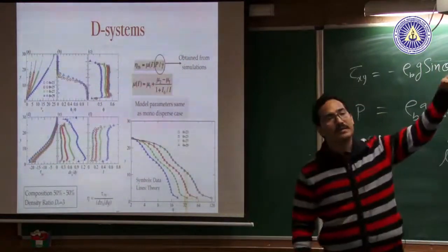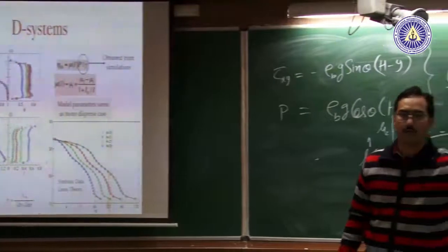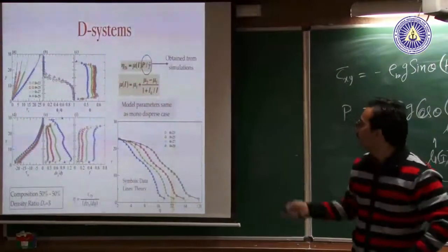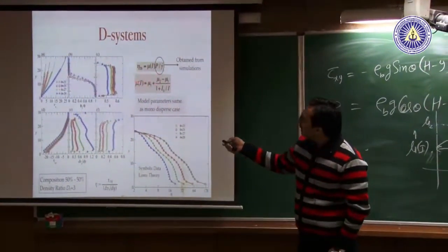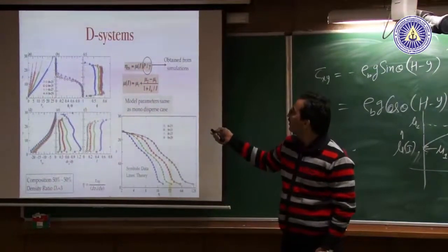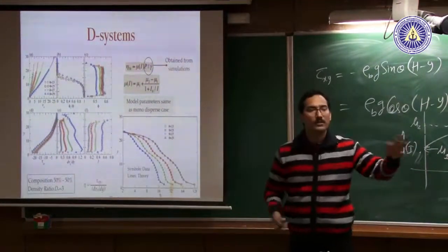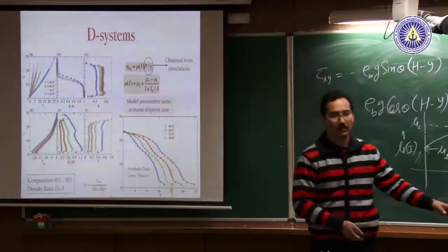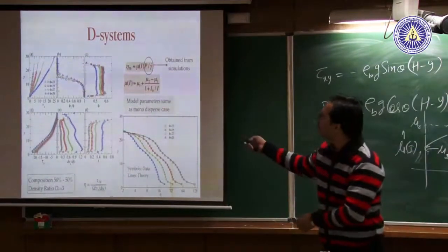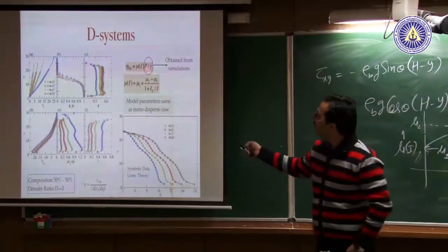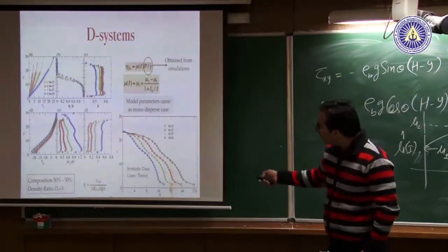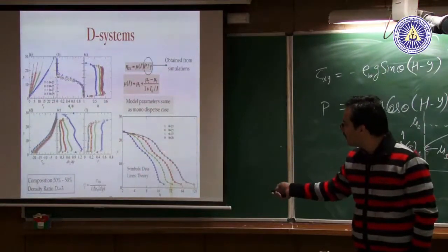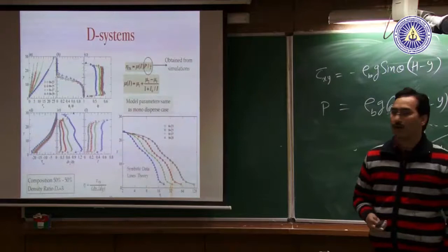I use the same parameters that I had for my monodisperse case. So the particles have the same restitution coefficient, same friction. The only thing that has changed is density and size. So then I can use the same model parameters, the same values of mu1, mu2 and I0. And just to make sure that my other assumptions are not causing any difficulty in the verification, we are taking the pressure and gamma dot from the simulations, and then we'll see if we can get these also from theory. But to begin with, we're just asking whether the same rheological law works, and it seems like this complicated variation in viscosity, where you have only heavy particles here, only light particles here, can be captured pretty well.